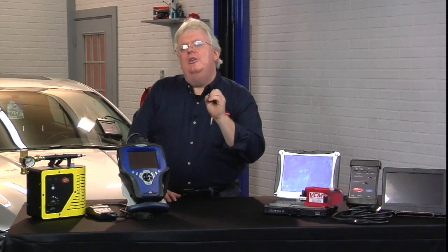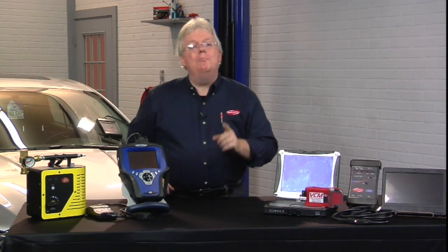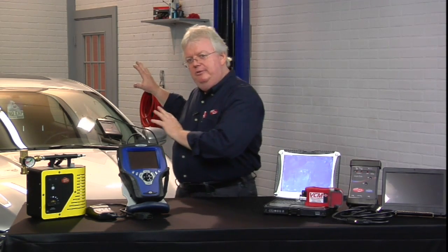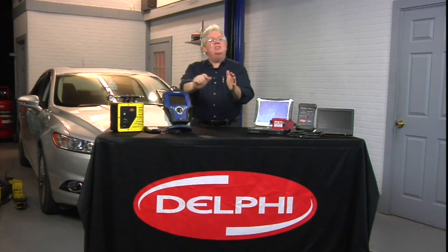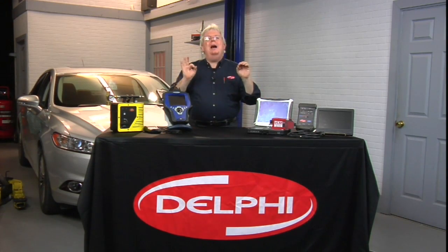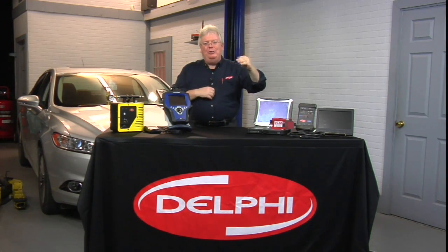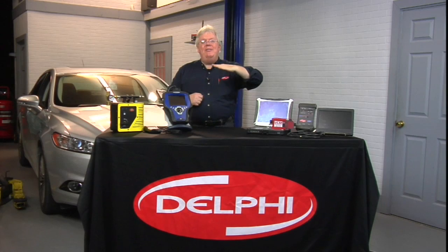And it certainly won't catch, you remember the code I asked you to take note of? The 443 EVAP solenoid circuit. That's not going to catch a circuit problem. Your meter and your scanner will catch circuit problems. So this is why we're seeing, when we have an emissions related P0443 light, and that's EVAP related, and EVAP is one of our non-continuous tests that we always find in mode 6, why we're not seeing the reds, we're not seeing failed MIDs and TIDs, because the test never ran that far.